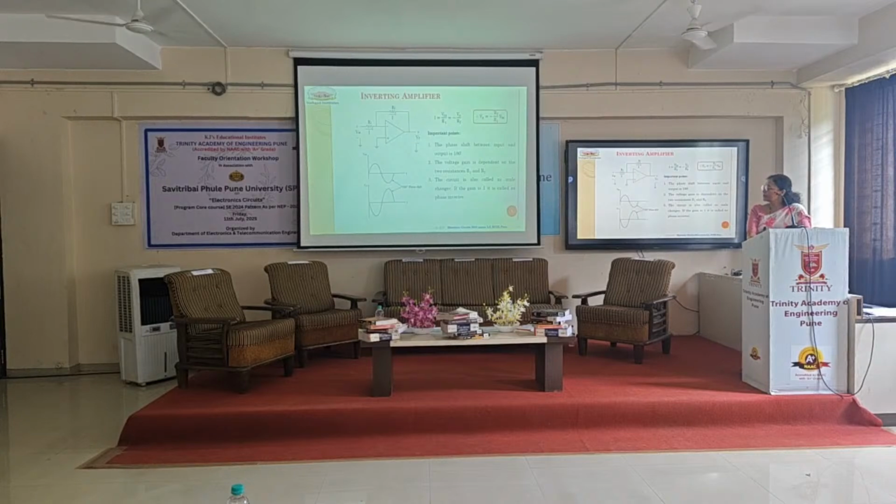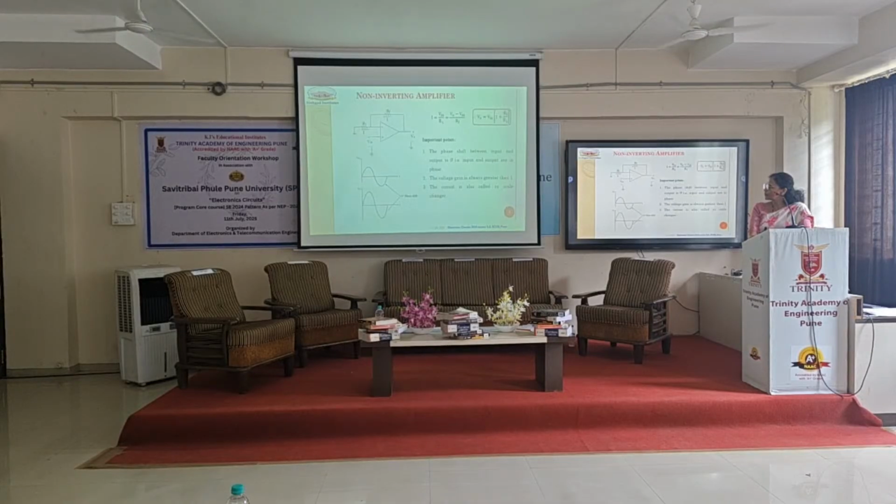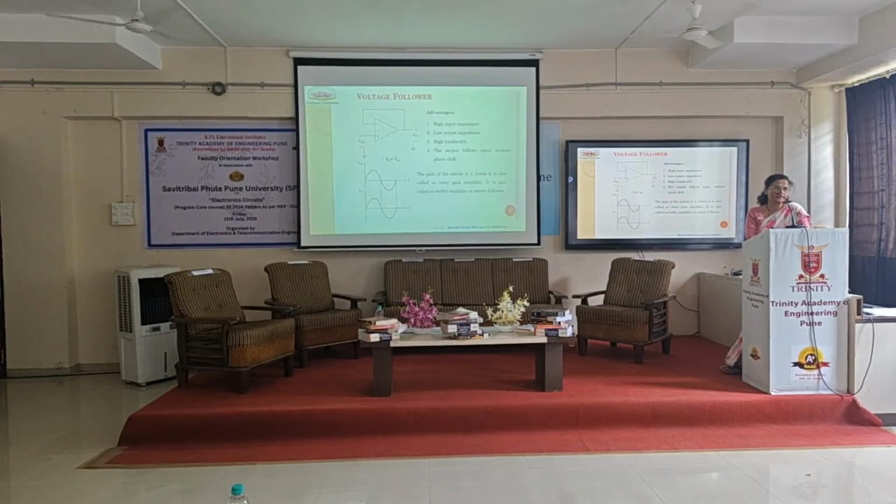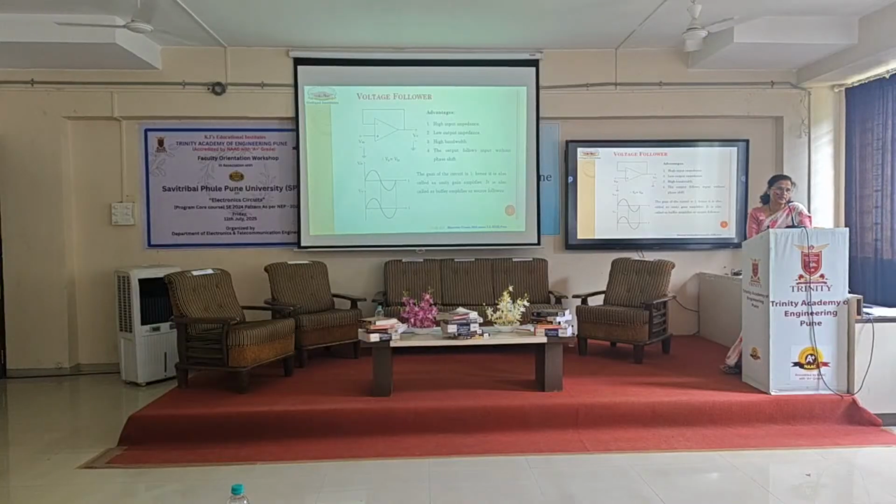Same points are coming here under the inverting amplifier derivation for the voltage gain. Inverting and non-inverting. And third point is voltage follower. It is an extension of the non-inverting amplifier but with unity gain. And the main application is that it has very high input impedance.